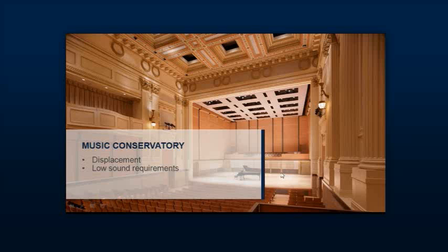Hats off to them. My favorite place to use displacement actually is in churches. This came from an analysis I did about 12 years ago where we had a historical church. They wanted to renovate, and churches have this typical natural stack built into them, particularly cathedrals, where we have a bell tower that acts as sort of a chimney. In the traditional European cathedrals you have windows along the perimeter for the pew area, and you would open them up in the summer, the cool air would pour in, and then the heat would rise up and draw more air in.